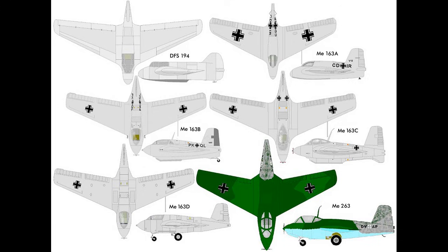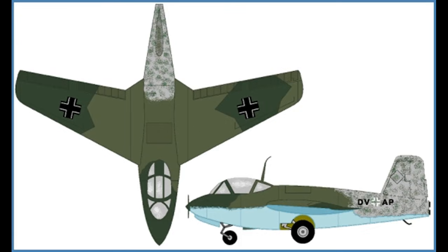With the dual-chamber rocket, it had an endurance of 12 minutes. And that's a 50% improvement over the 163, but more significantly, because of all the fuel burned in climb, it had a lot more left over at the top of climb, and its time in combat from top of climb until it had to start its glide back down doubled. So going from 8 to 12 minutes was actually very meaningful. Now, I've read speculation that its burn time could have been extended to 20 minutes had they got it into production.